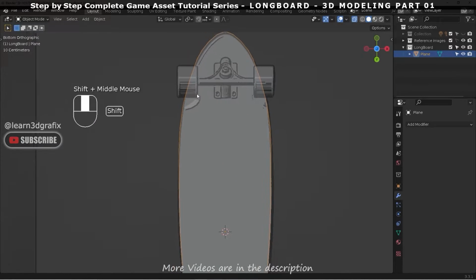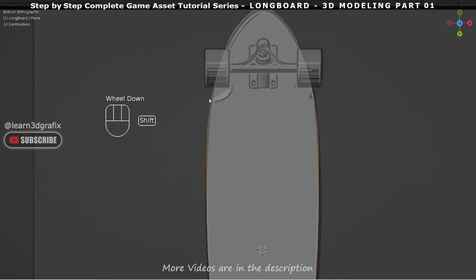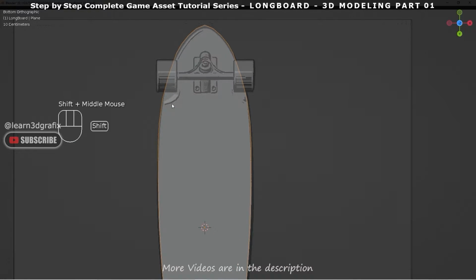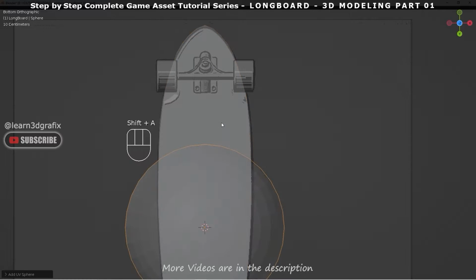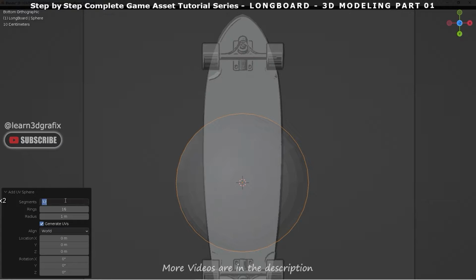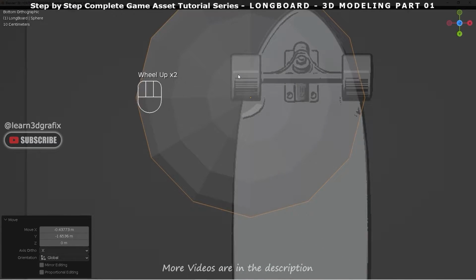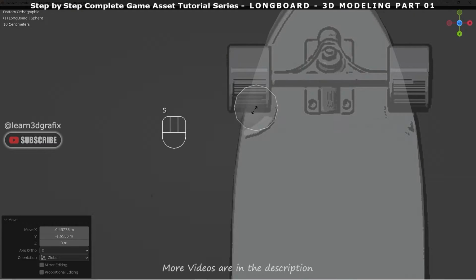Now we have to create this cut. We will use the Boolean method to create this cut. Press Shift A, go to Mesh and select UV sphere. In the UV sphere properties, segments would be 12 and rings would be 8. Now scale it down.